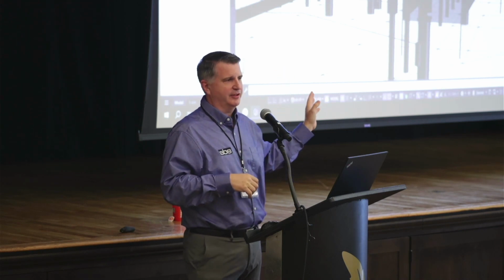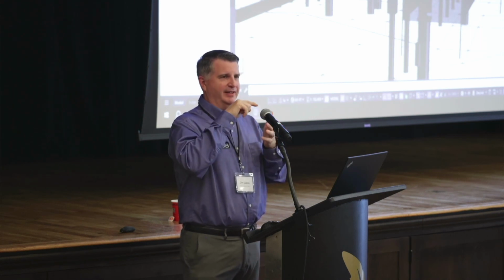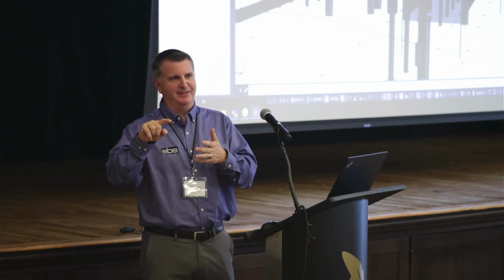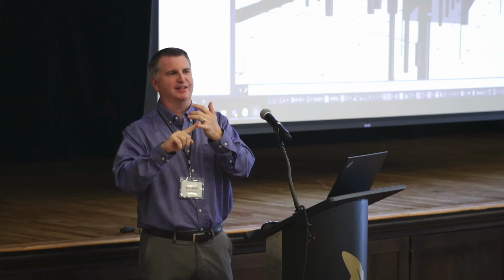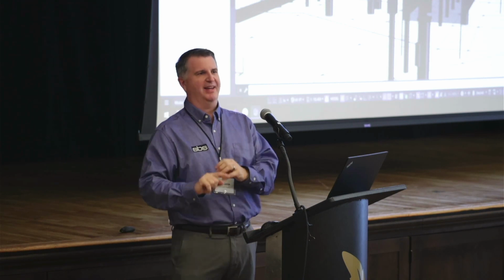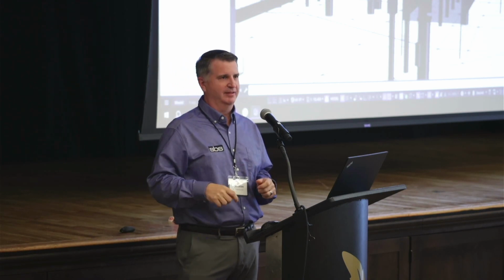What you're seeing on the screen, I can literally tell you that it starts with this connector, goes to this conductor, sags to this step, goes to this connector, which is on a connector, which is on a connector, which is on an insulator, that goes to a structure, that goes to a pad. Like, I know every single piece of what's going on in that substation.